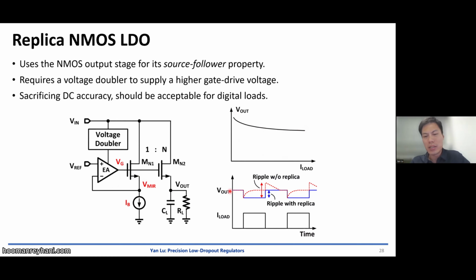with the DC load line technique, but this is not the DC load line technique, right? Or the adaptive voltage positioning. We like high output voltage at light load. That means we have more voltage headroom for the LDO to drop, right? Then at heavy load, we have low supply. It has more headroom for the output voltage to go up for the overshoot. So in terms of load transient, this is a good phenomenon, right?